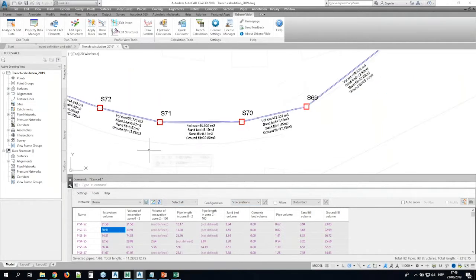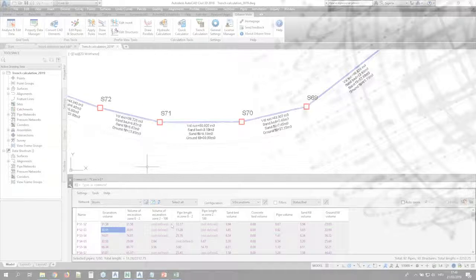So if you're using property set data, you can really get several improvements together with Urbano Visio. You can, of course, go beyond just showing the information in the labels. You can create a CAD table, you can export this information to Excel, you can analyze on it, and so on.